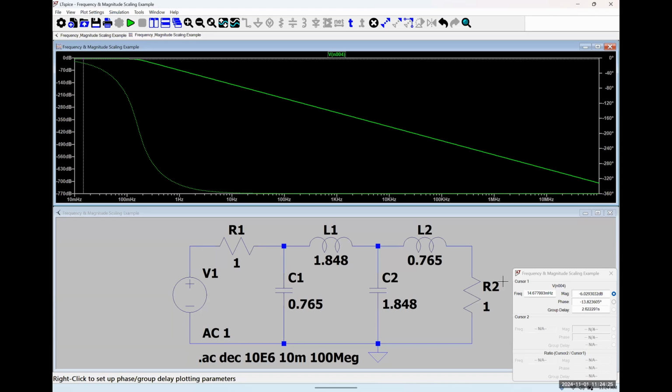So our corner frequency or our cutoff frequency should then be at roughly -9 decibels, because it's 3 decibels lower than the maximum value. So if I slide this thing over and I look for where we hit -9 dB or something really close to it, we're at 159.5-ish millihertz, pardon me. I said that this thing was designed for an angular frequency of 1 radian per second. So what's the problem here? Or is there a problem, I guess would be a better way to put it.